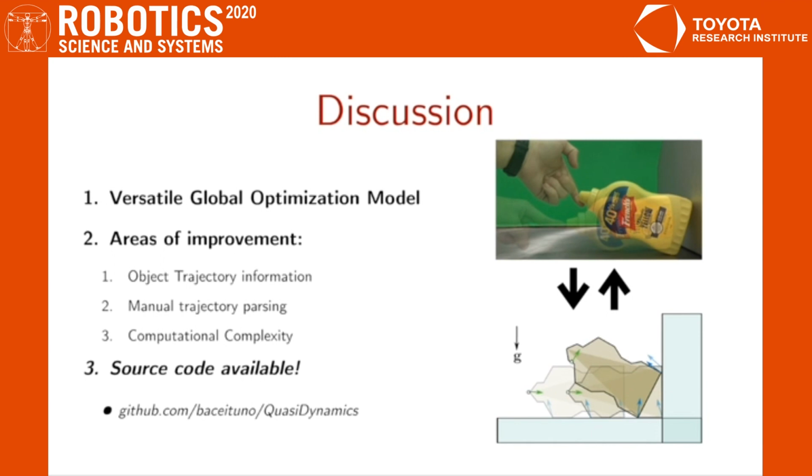This, however, has several limitations. First, since we assume the object motion is given, the success of the algorithm depends on having a feasible initial trajectory. Second, our model assumes that the problem parameters are explicitly provided to the optimizer, this including object shape, friction cones, and external contact modes. Parsing these elements can be complex and very difficult, especially if we want to go to more complex scenarios. Finally, the mixed-integer programming formulation has exponential bounds in its complexity, growing with the number of integer variables. This constrains our problem to be only practical for fairly simple shapes and short to medium horizon trajectories.